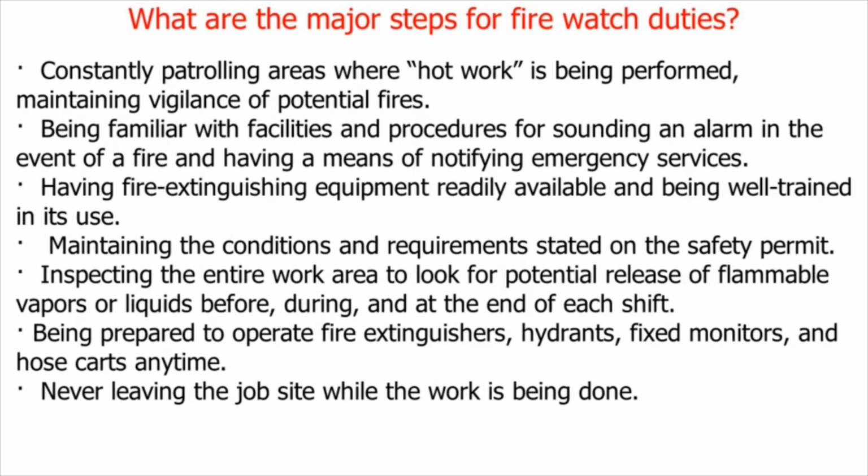Maintaining the conditions and requirements stated on the safety permit. Inspecting the entire work area to look for potential release of flammable vapors or liquids before, during, and at the end of each shift. Being prepared to operate fire extinguishers, hydrants, fixed monitors, and hose carts anytime. Never leaving the job site while the work is being done.